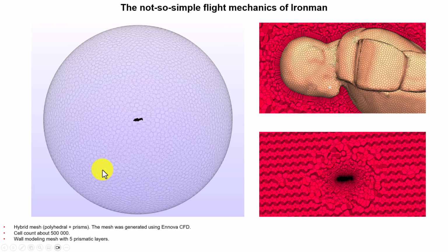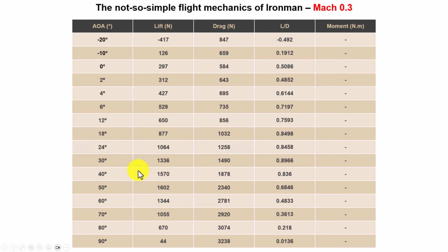Okay, so we have a mesh. It's a very good mesh. A polyhedral mesh, and the mesh is also wall resolving. We use a very good meshing tool. And from the previous video, I mentioned that to construct some polars, but I was a little bit conservative, or I didn't have an idea, so I mentioned let's go like 20 degrees, probably 10. But it turns out that I have to go from some negative value, actually starting at 0, to 90 degrees.